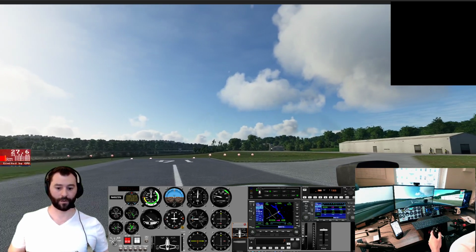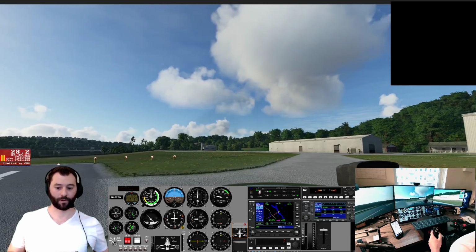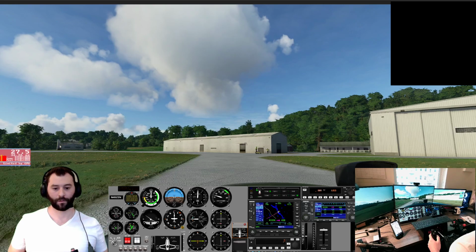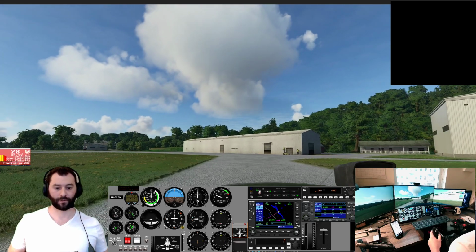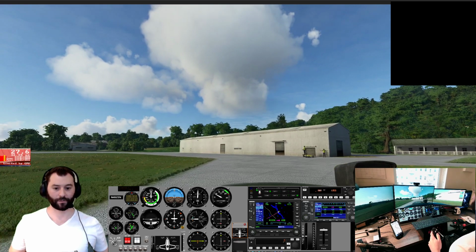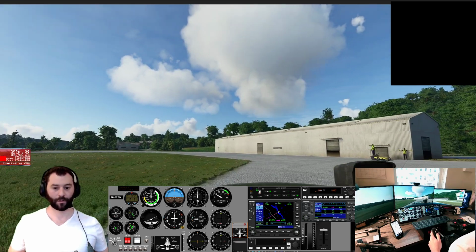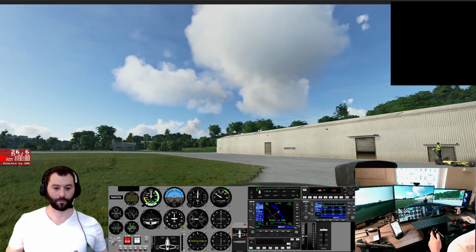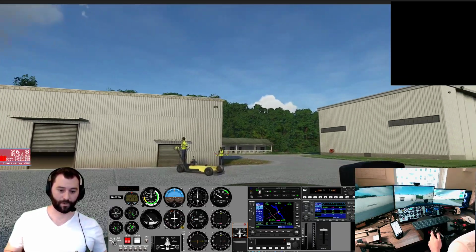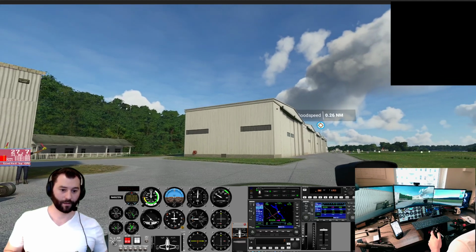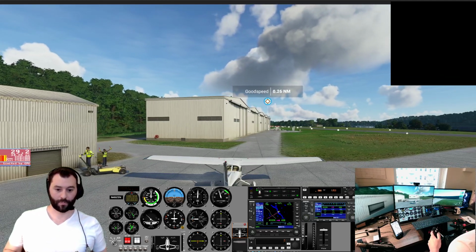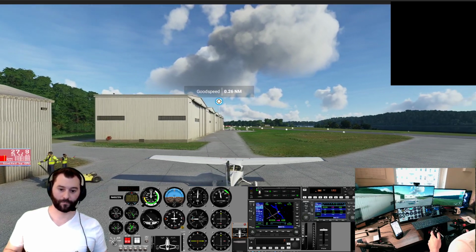Turn off the taxiway here. We're looking for 1,000 RPM again. We don't want to foul our plugs. So we're going to turn around here. We're going to hit our right brake and pivot around that. Going to give it some throttle. Whoops. Pivot around that brake.